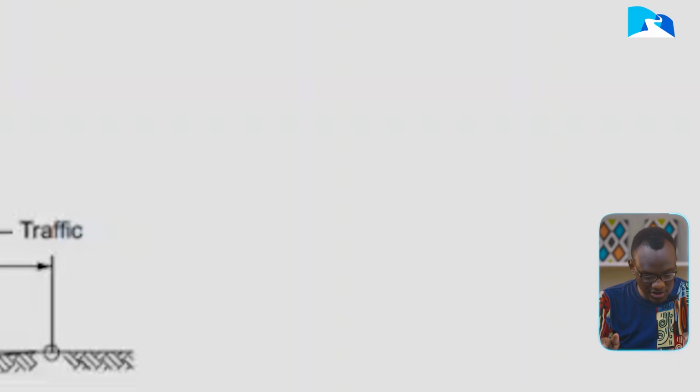You've maybe seen this everywhere you go. If you have a reverse curve, they're normally in the ratio of 2 times. If you have a given radius at one point, you have to get it 2 times the other. As we're highlighting in the notes, they are normally continuous. So we have symmetrical reverse curves, which means the reverse curves are symmetrically equal.